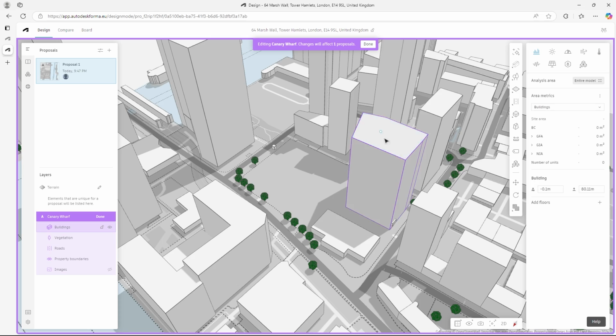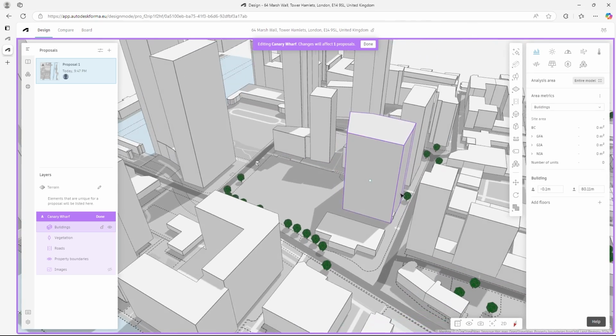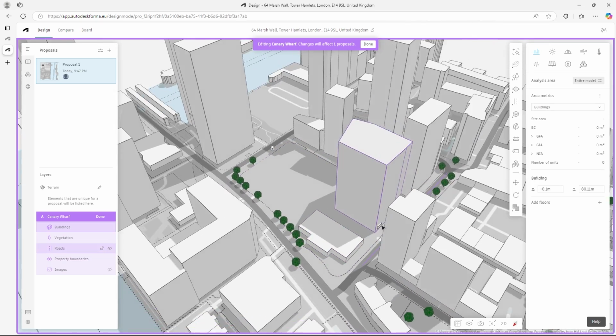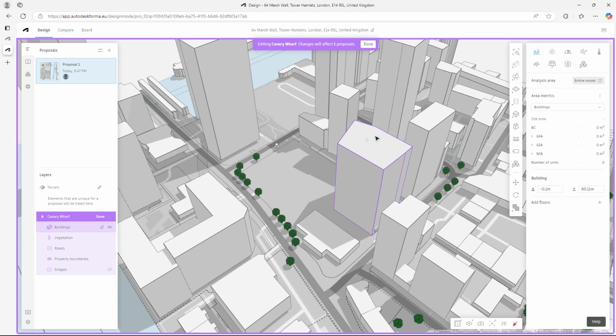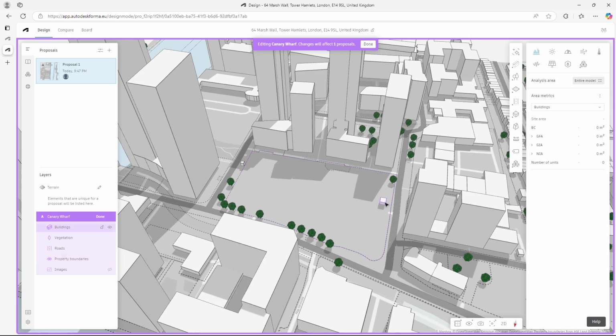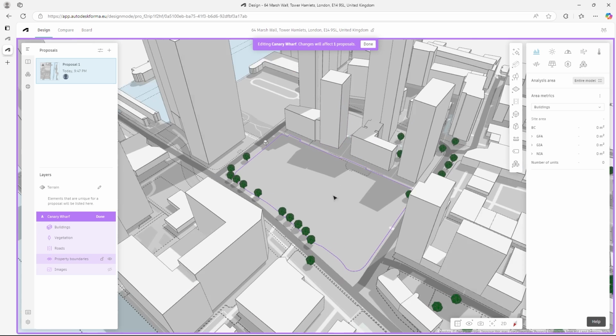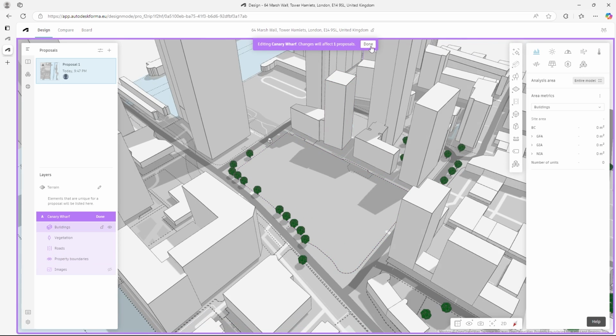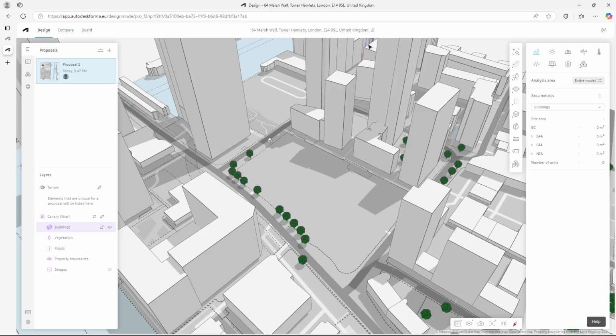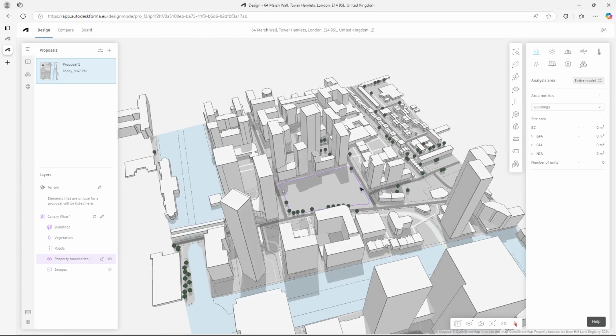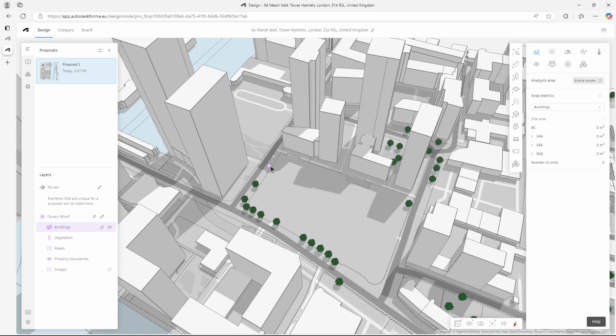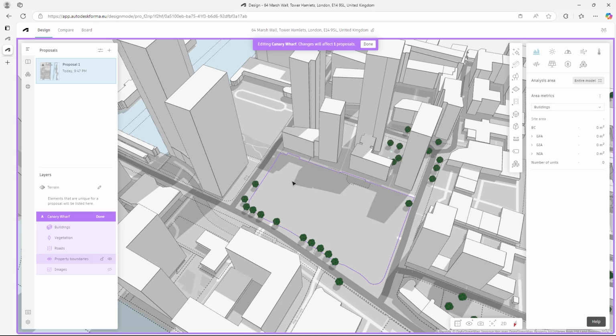You can also change objects in your base. If you, for example, see a building which is not the correct height, then you can change that. I'll get rid of this one. I will also get rid of this one and this small one here. And when you're done with editing, you can just click here, done. All right, so now we have a clean plate and oh, there's another small building. Let's get rid of this. Edit base and delete. Done.